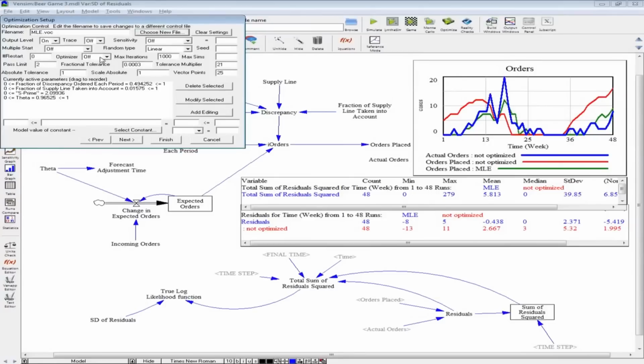In addition, specify sensitivity test by choosing payoff value and entering the value by which Vensim will change the optimal likelihood function in order to find the confidence intervals. Because for likelihood ratio method, the likelihood ratio is approximated by the chi-squared distribution, it is necessary to find the value of chi-squared distribution PDF for 95th percentile for 1 degree of freedom, because we are doing the univariate analysis.